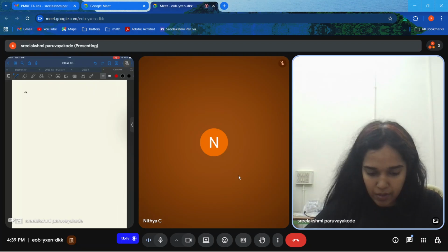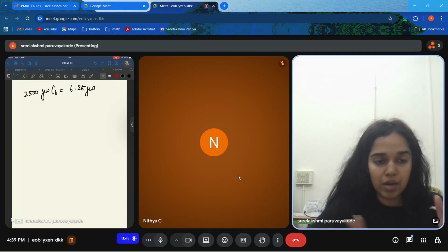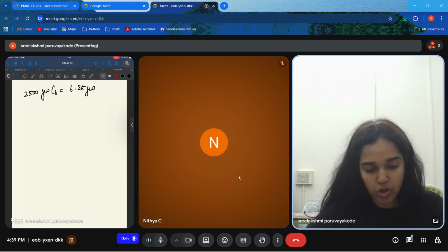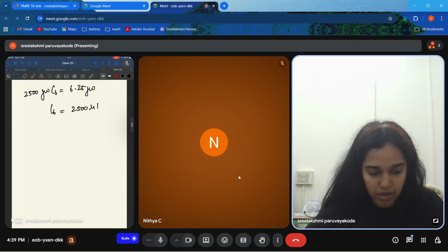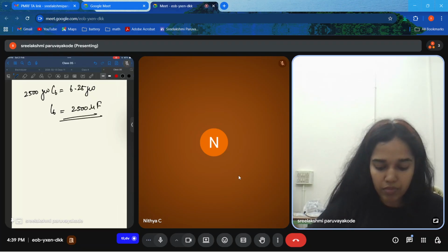Finally, in one step, you will write something like this: 2500 j omega C6 equal to 6.25 j omega. Why? Because other terms are all numerical numbers, they will get cancelled out. So j omega will get cancelled, and you will get C6 as 2500 microfarad. This is how you have to solve the question.